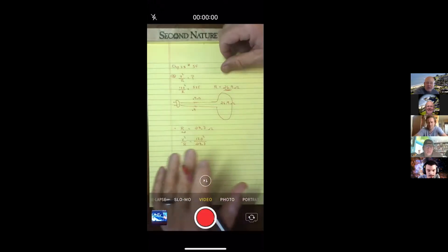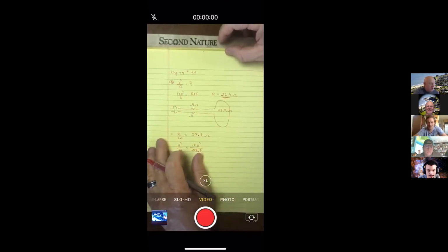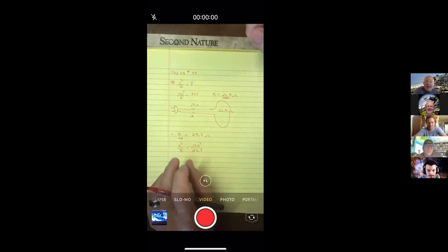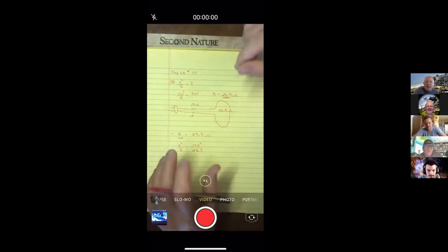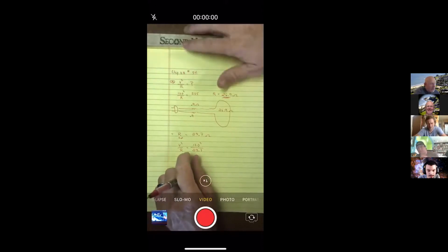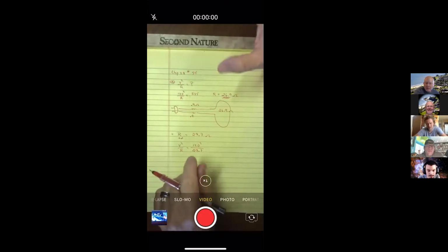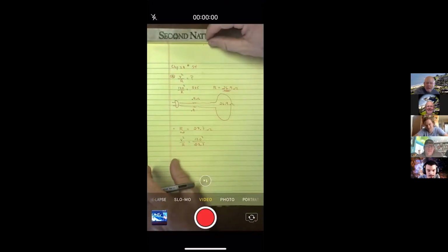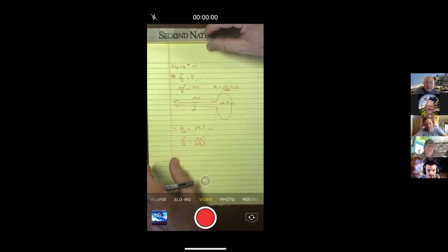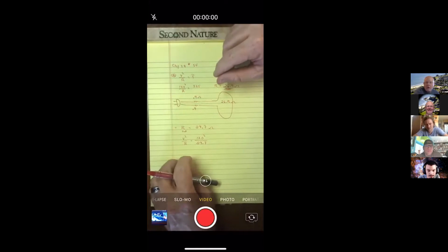It was just stuck. So then I disconnected the extension cord, and when you plug it straight into the wall, the lights dim and it just barely starts. Somebody designed this compressor, obviously, to be right at the maximum, but not require 240 volts. A lot of compressors run on 240 because they take so much energy. But I got this one because it was the most powerful one I could find that would still run on your regular 120 volts.